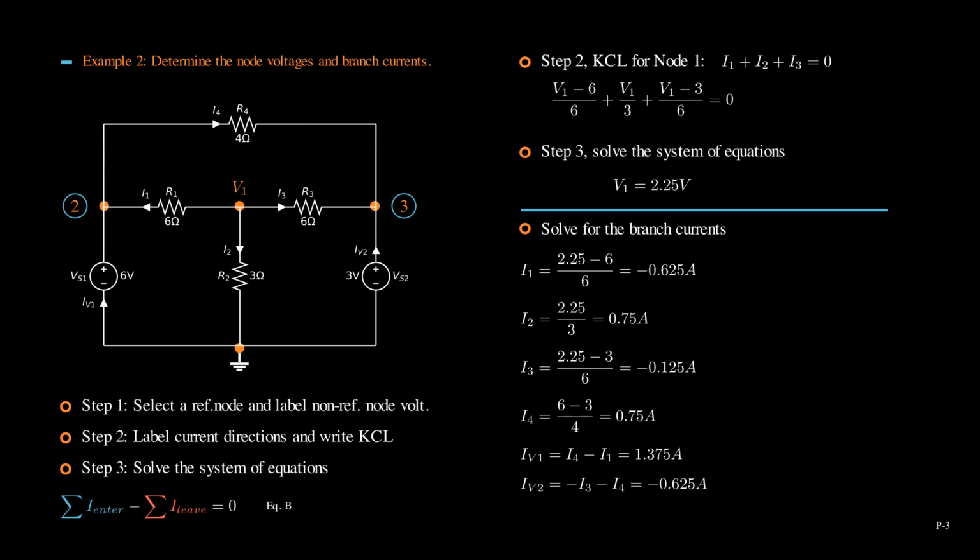A final comment is that, using node analysis, no matter what the question asks you to determine, our goal is to find node voltages. Once we find node voltages, everything about this circuit will be known.